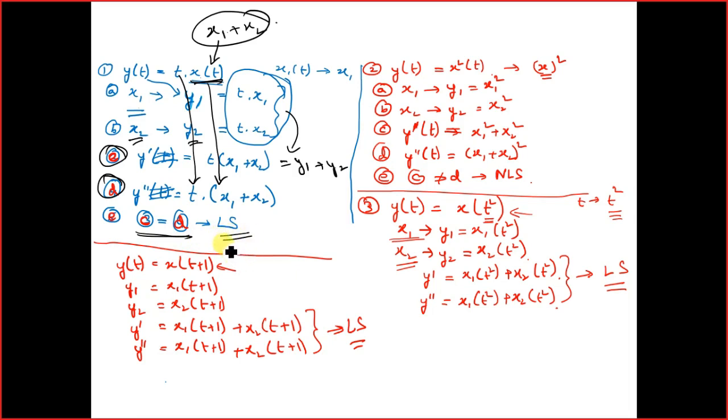And this is nothing but your linear system. You can correlate this with the inverting amplifier example, which I said just a few moments back. In one case, you have the input 1 volt, you got 2 volt. When the input was 2 volt, you got 4 volt. When I add up these two values, y1 plus y2, I get 6 volt.